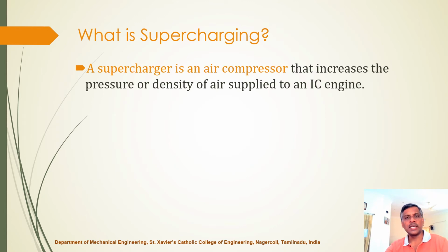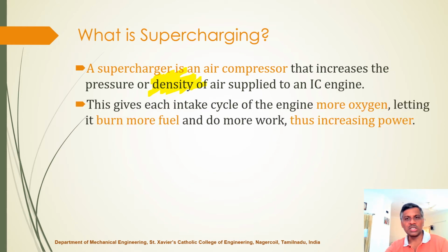What is supercharging? It's an air compressor that increases the pressure and density of air. Pressure means density of air. So compressed air is supplied to the IC engines. So more mass of air is supplied. More air is supplied, more fuel can be burnt. So the intake has more oxygen, allowing more fuel to be burned, and you'll get more work, that means more power. That is the purpose of supercharging. That is the word supercharging. Charging more. Charging is supplying more fuel. That is possible because you can supply more air.